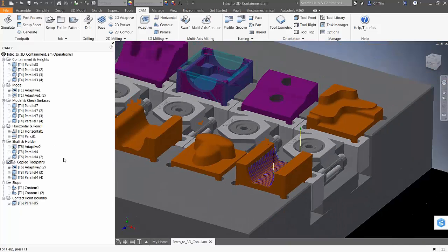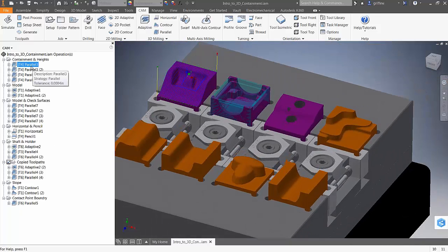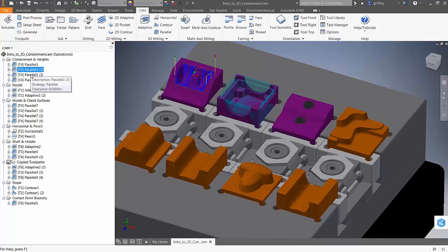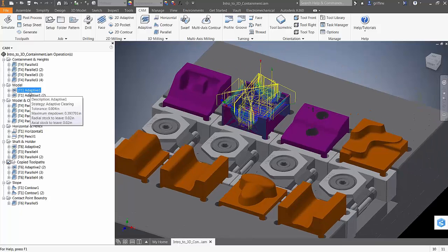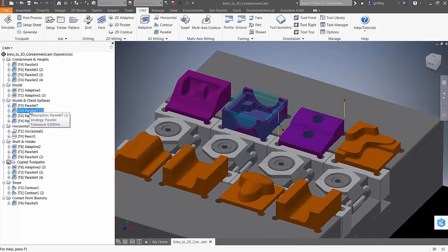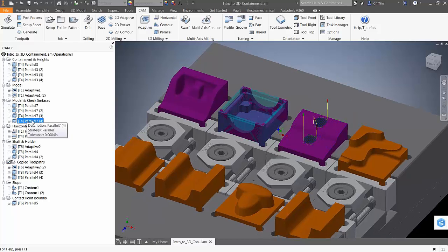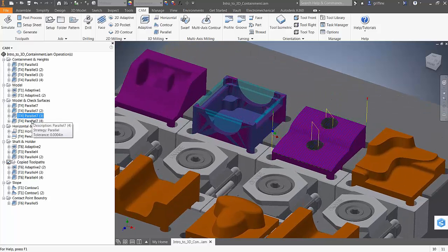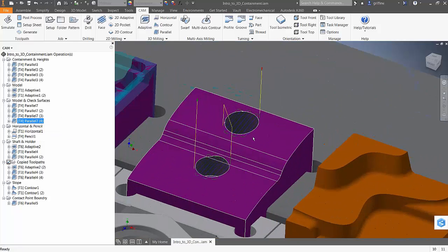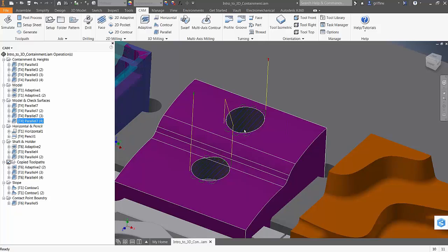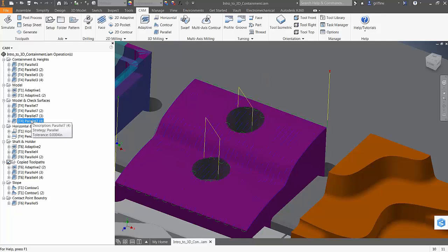So we've looked at a lot of different ways we can contain the toolpaths. Okay, we select geometry. Model override is another way to work with it. Using model override where we can avoid holes using surfaces. Also touch surfaces we can work with to contain the toolpath within a surface region, and also to let you know you don't have to have surfaces drawn. You can select any region on the part and use that as a driven surface where you can contain your toolpath.